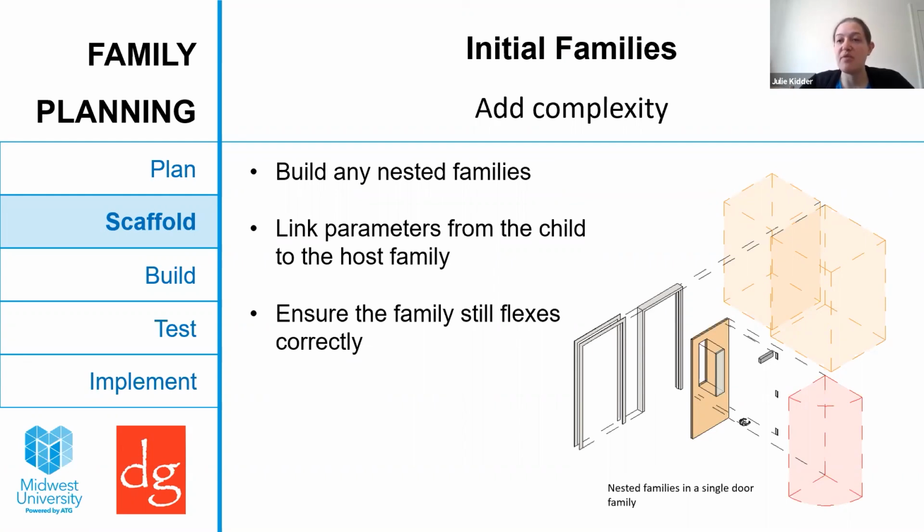And then it's up to the user to make sure that name matches the family type that should fit in that slot. I would love a way to put a filter on those family type drop-downs and say, only if the name begins with this, show it, but that's not an option. So that's the solution I've come up with that meets the needs we're working with a minimal amount of side effects, given what our options are.